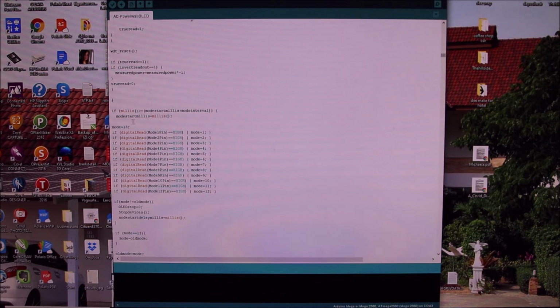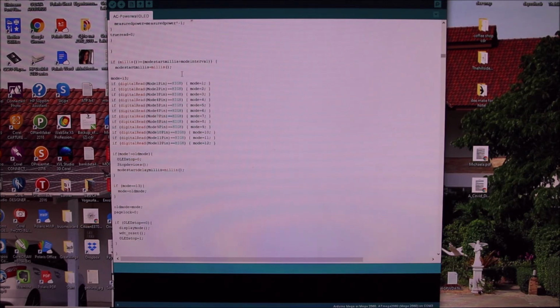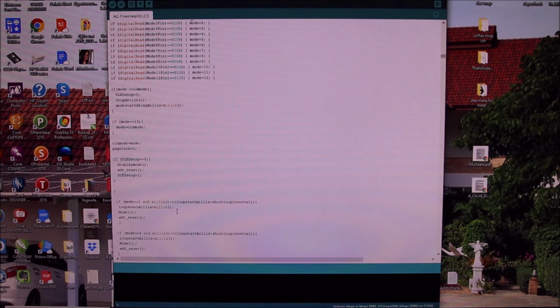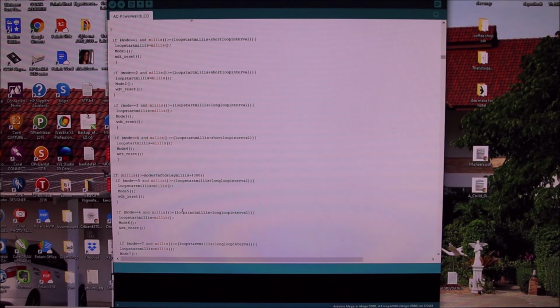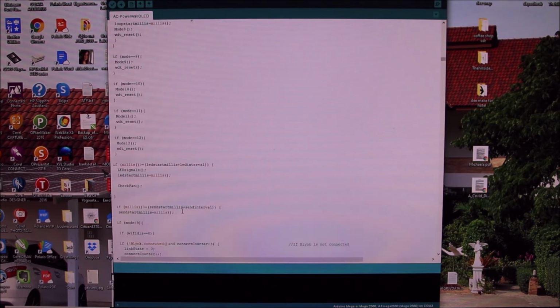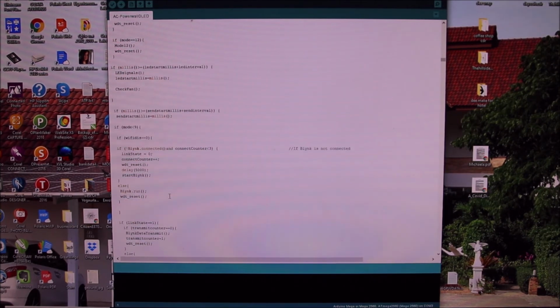It is just saying, okay, if so many milliseconds have passed, then please do this point. So please check which mode is activated, where the switch is standing, and then do the mode if that time has passed, etc. So it is non-interruptive. A non-interruptive loop is very important in this case, because if you put interrupts into this, you will destroy Modbus or whatever.